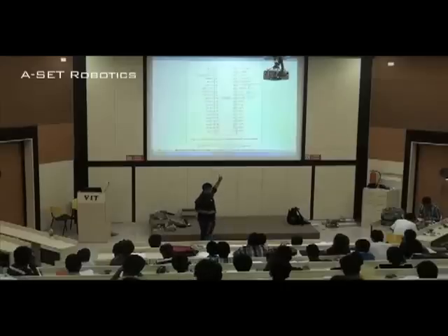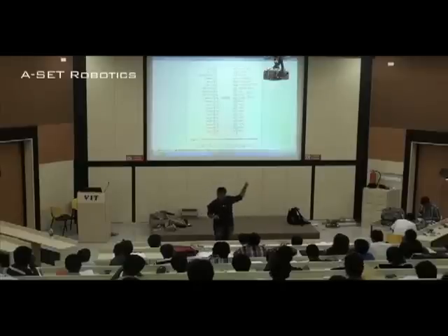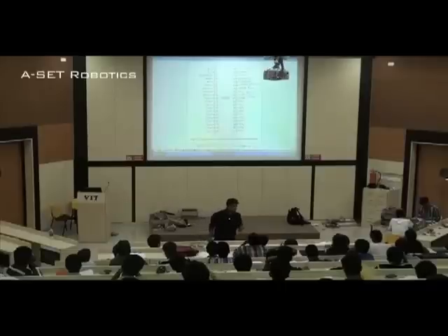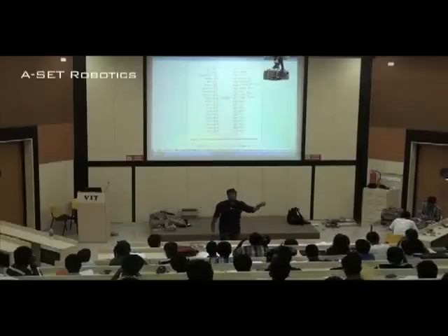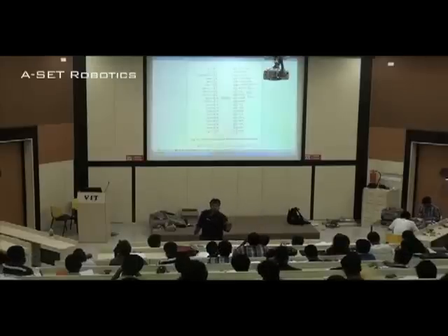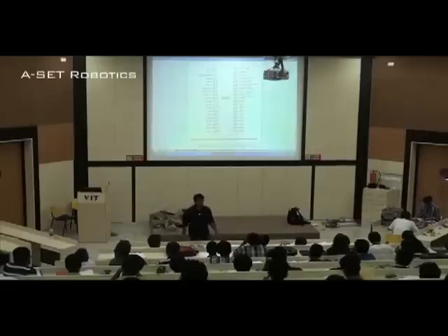If the RD pin, the read pin, goes low, that means the microprocessor is going to read from the memory. If the write pin is low, that means it will write some data that is there on the data bus onto that address location. Got it?